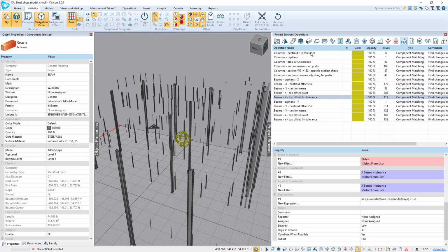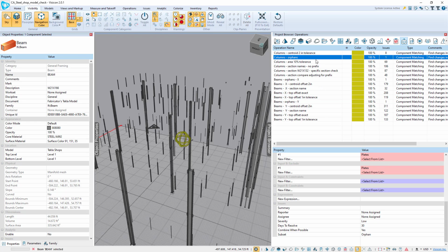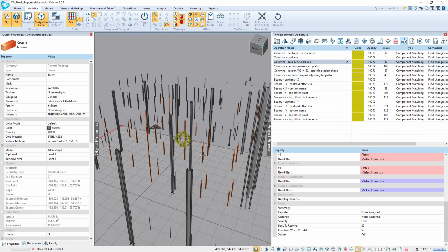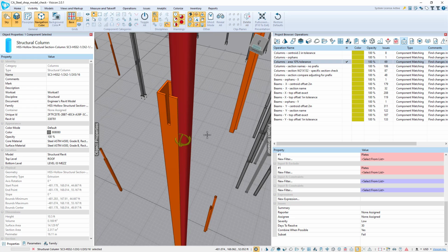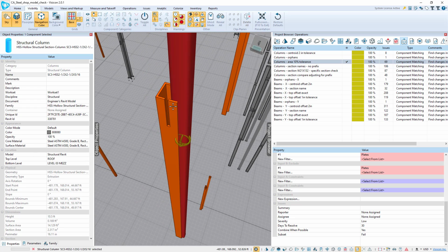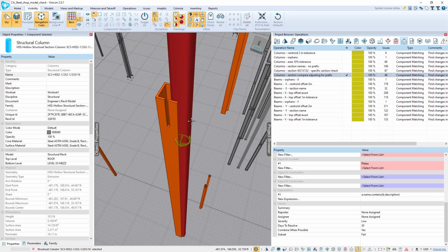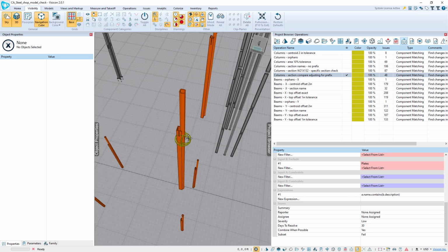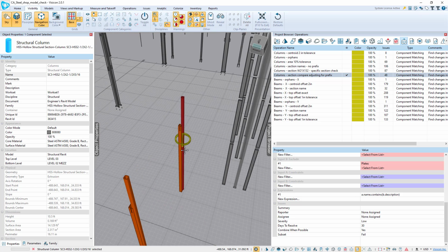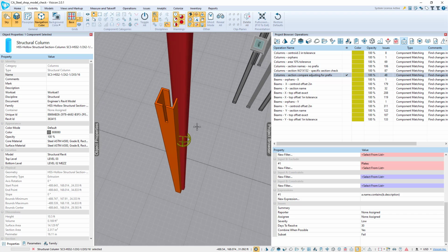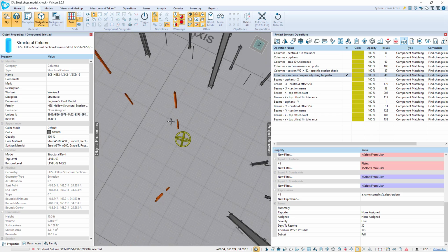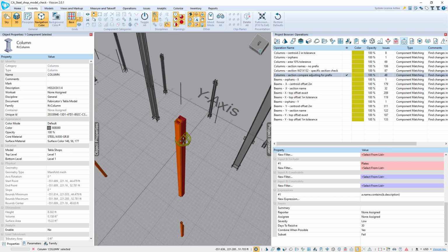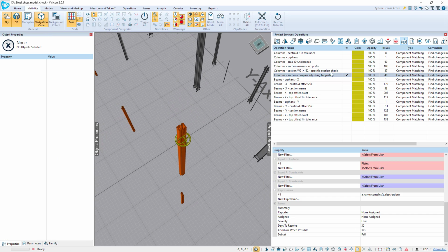Under the columns, again, same type of thing where we have our orphans, area tolerance. If I turn on area tolerance, again, we're just isolating where we have problems, and I can see clearly there's a problem. This section is not the same as that section. I can go in and specify names and the descriptions. Now, this one gets picked up because obviously the area might be off if the name is off. Again, these are all places where I'm always just looking for color where I have the offset, right? So we're finding all of these locations.